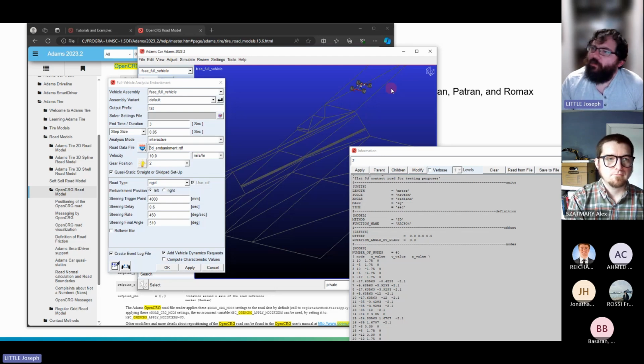It's pretty robust. It's been around for almost 20 years now. If you were in Adams View trying to build a four-bar link or something, you should definitely start from scratch, and that's a good exercise in Adams View. But in Adams Car, it has to be fully compatible to do full vehicle analysis, and fully compatible with the full vehicle control rig. So building from scratch is difficult. I would definitely recommend starting with this model if you're building a Formula style car, or worst case, start with some model that already runs and modify from there, one bit at a time.